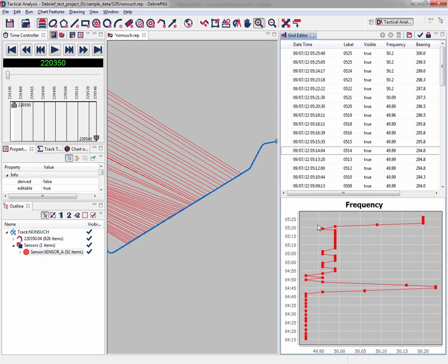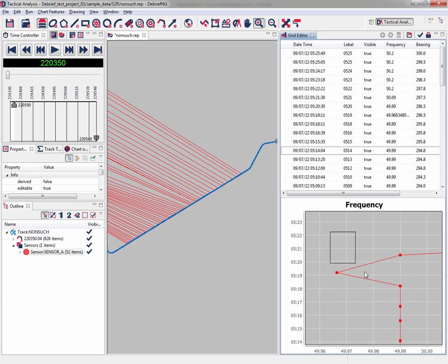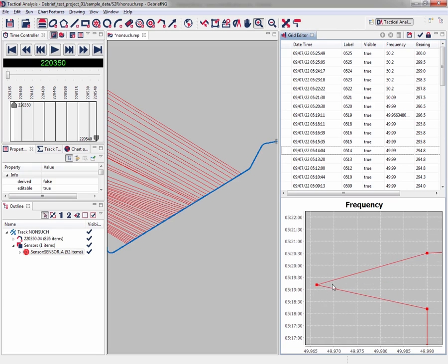Now we're looking at all the frequency data. You'll see that while the data seems fairly constant near the top of this data set, the data value is too low here, around about 0.519, when viewed in the context of the steady track below it and the value above it. So as such, we're going to fix this data point by dragging it into a better position. Now we can do that from here if we want by clicking on it and dragging it, but it's going to be pretty imprecise. So of course we zoom in. And you can do this multiple times, and then we click and drag.